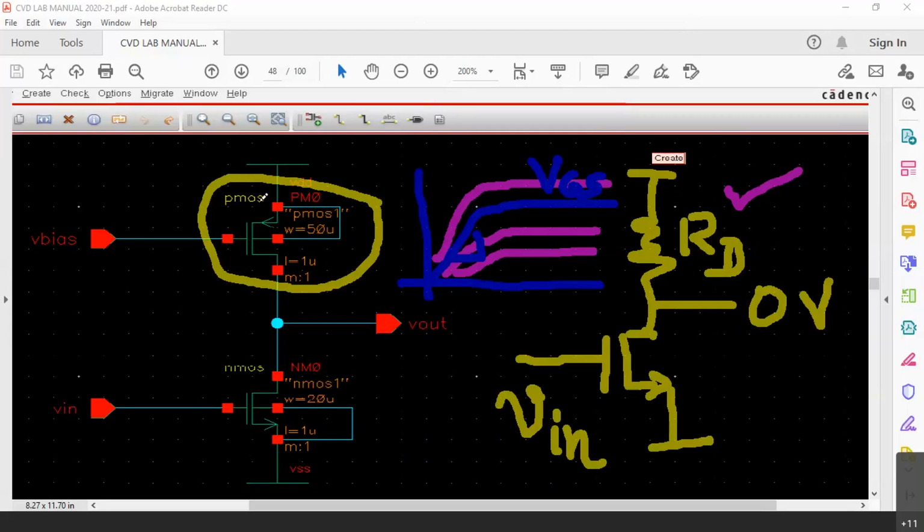Right now, this is a pull-up transistor only, right? Pull-up in the sense you will have a resistor at the top, that is called pull-up. If you have a resistor at the bottom, it is called pull-down. Now, in this case, the bottom transistor is the amplifying transistor, and the upper transistor is the one which is being replaced for the resistor. So, it has to be pull-up only.